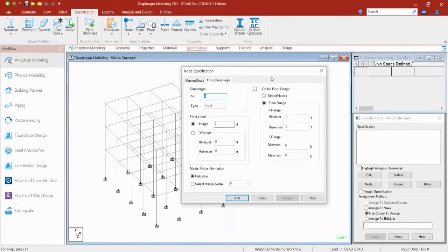Inherent eccentricity happens when your seismic loads are applied to each level of the structure at your center of mass, but then resisted through your center of rigidity. If your center of mass and your center of rigidity are not the same location, you could create an additional moment arm that is going to add some moments to your seismic load. The floor diaphragm will have that capability. This will unlock the inherent torsion available within your system.